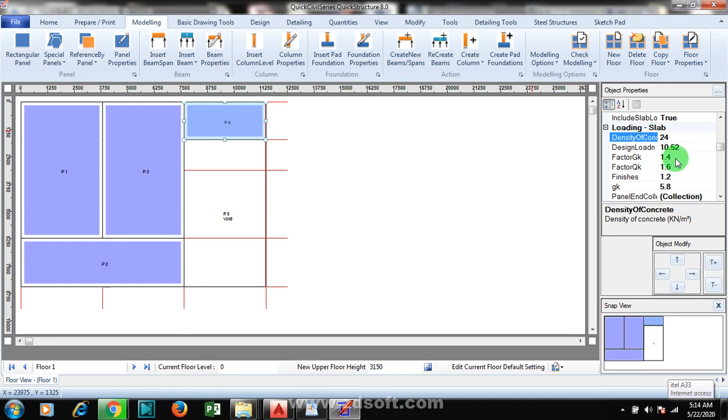Okay, you can see your live load is 1.4. Sorry, your dead load is 1.4, your live load is 1.6. Your finishes is 1.2. All of these are editable. These are not constant. Your finishes are not constant values that you have to cram. I will advise you on your finishes, your partitions. All of these loadings are mostly affected by the category or the class of design.